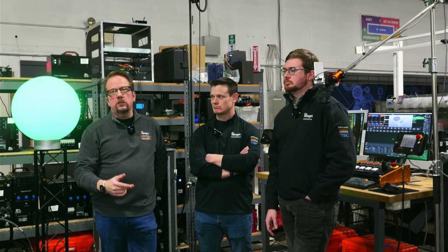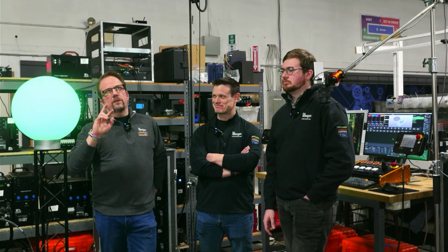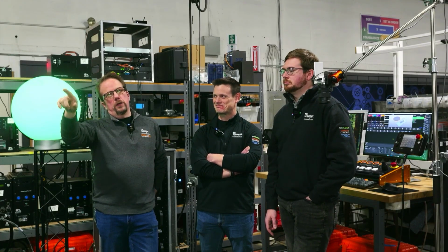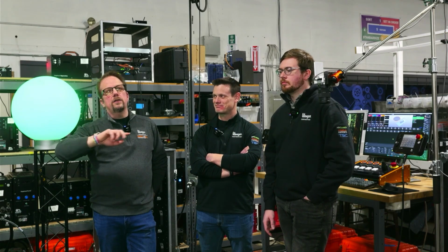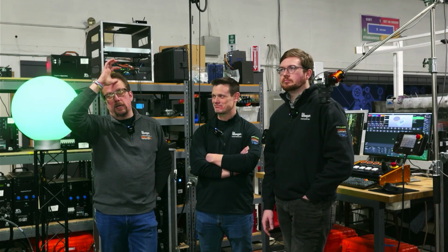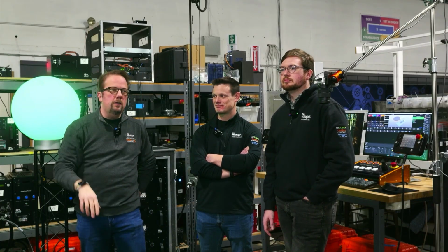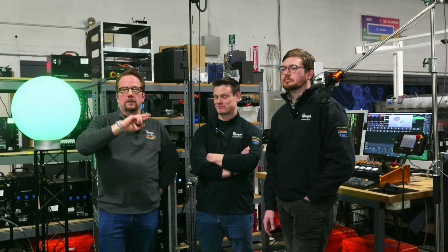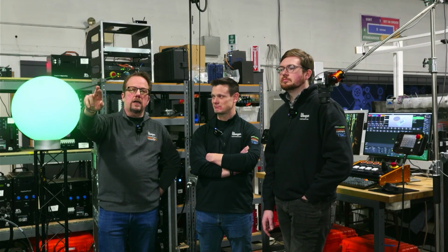The limitation in terms of distance, there are inputs and outputs, right? So the outputs go out to the contactors, the safety relays inside each Stagehand. The biggest problem there is just voltage drop over the gauge of wire you have. So we have tables that will tell you how far away you can be. It's quite a distance, so we're into the thousands of feet kind of range.